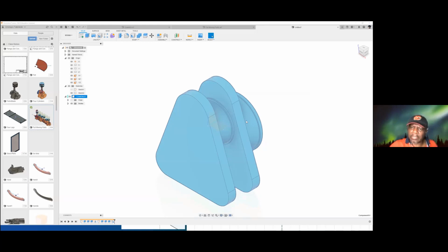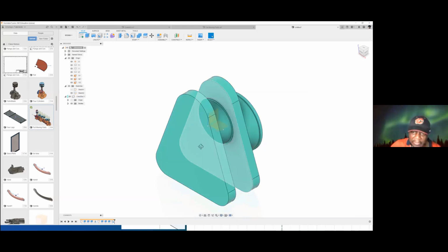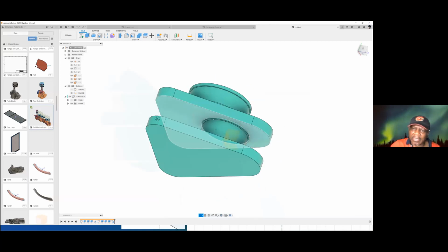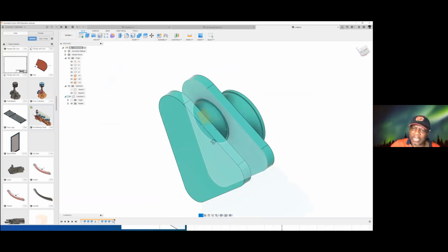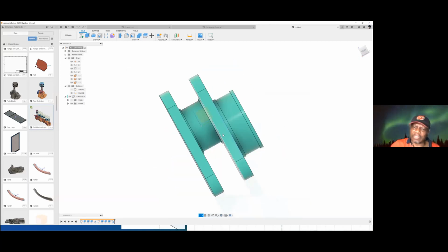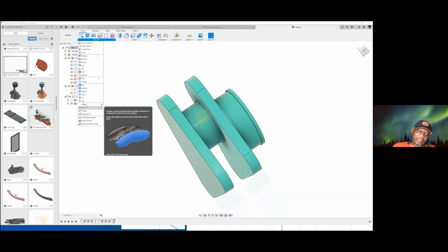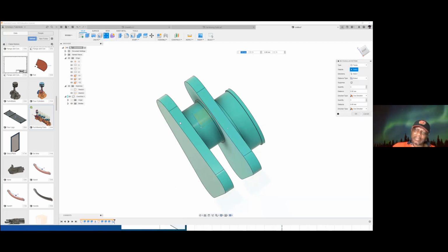So that is that. So this whole thing now is a whole component. So we can now replicate this. So let us say I want to make 2 copies of this. So I can create a pattern replication, rectangular pattern, and the type is components, and then select a component. This component is selected.